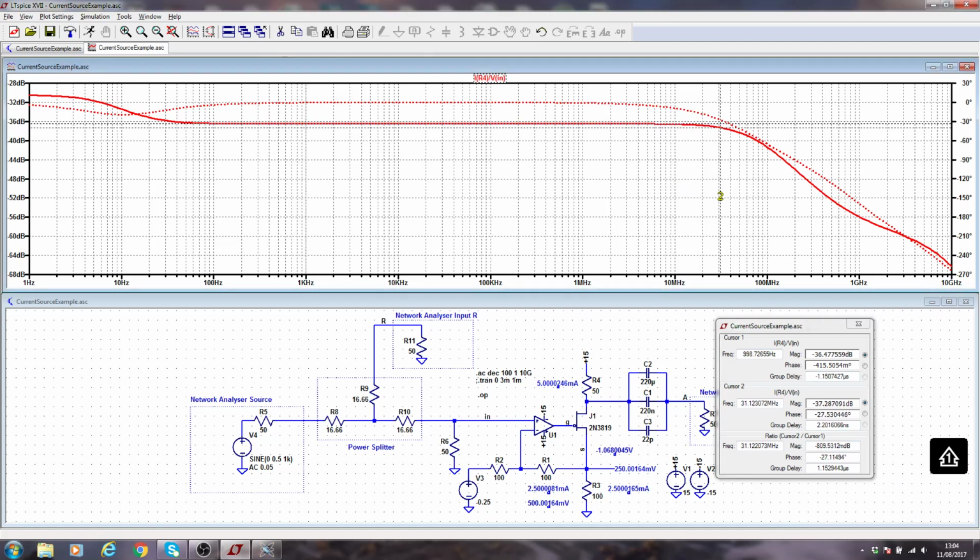So I keep going, more. Oh, nearly. Little more. I can use the cursor keys now to adjust it, and these are the 2 nearest data points. So I'll probably take that one, because it's the lower frequency and we are hoping for big bandwidth, so this is a conservative estimate. 67.6 megahertz. This is actually the difference between the two. The frequency we're at cursor 2 is 67.608, not 607. The reason for that is I dropped the first one at a kilohertz, and that's the reason for the 1K difference.